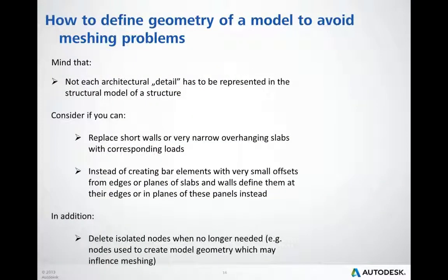At this point, I would like to introduce a couple of tips that you may find helpful. First of all, mind that architects naturally create models that contain all the details, and our job is to simplify that. You definitely don't want all these details to be transferred one-to-one to the structural model.